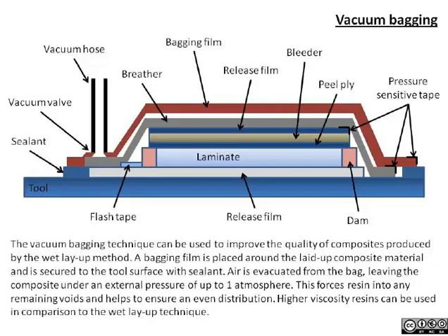This has a couple of advantages. First, it applies a little bit of pressure normal to any of the interfaces that we might need to achieve adhesion on within that laminate. Second, if there are any gases being produced during the curing reaction, it assumes that they continue to evacuate, and we don't put any back pressure on the cure reaction, chemically speaking, and we achieve a good full cure. And third, it ensures we have good heat transfer if we're doing this in an autoclave, for instance, and we need to uniformly raise the temperature, although typically that will be achieved through that big metal backer plate if it's all placed at elevated temperature in an autoclave.